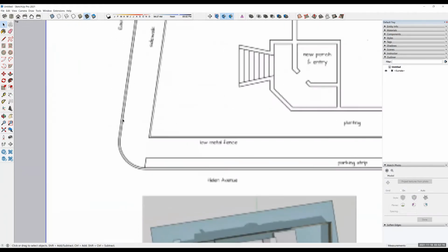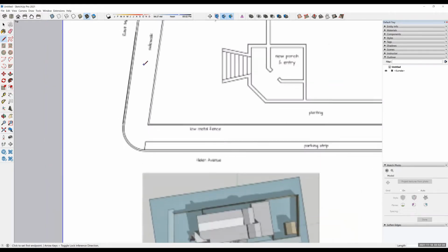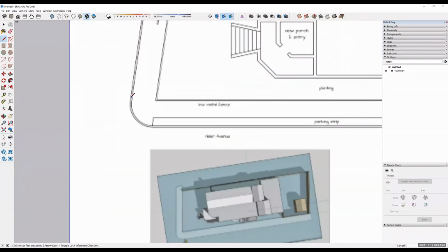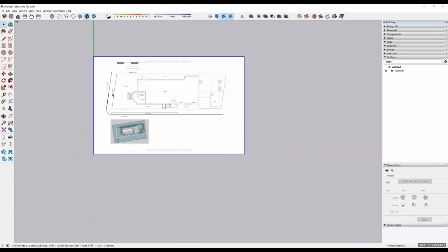So what I'm going to do is draw one line to align this building. It's still not precise. It looks not precise, but not wrong as well. Okay, probably I'm going to draw one line right here, along the solid green line. We always consider in SketchUp's three-dimensional world that the solid green line is the true north.